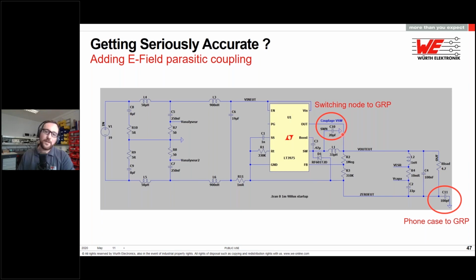So as you can see here, I have removed the direct ground connection from here. So my circuit is floating, and here I got my positive supply, here I got my negative supply, and you see this is now the ground reference plane symbol. So with my ground reference plane symbol, I just have to add the capacitance value here to model the common mode contribution.